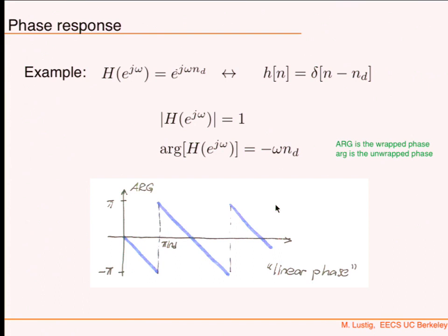And so this is very interesting, because what I could do now is look at arbitrary phase filters, and from there, if linear phase is the delay, I can try to analyze what is the delay of nonlinear phase filters. And what does it even mean?